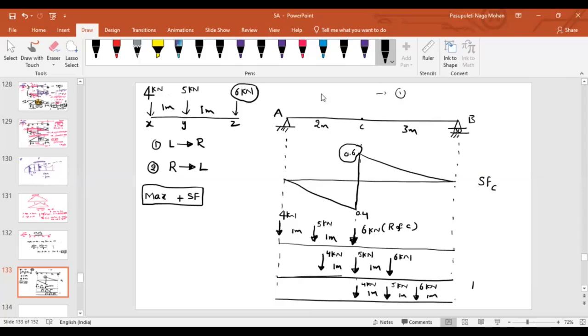Is it right? Other than these three possibilities, is there any possibility that I should check? No, sir. Everybody will agree to this. So if there is a series of loads, we have to see the possible combinations where we can get the maximum values. So in this case, what I have been doing is placing every load at the maximum ordinate such that I might get some possibility.